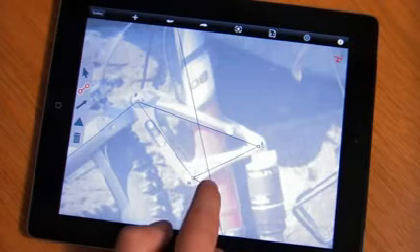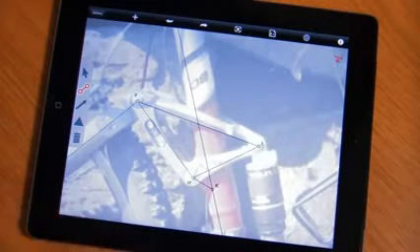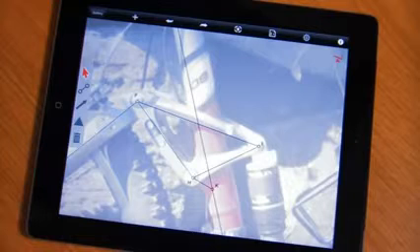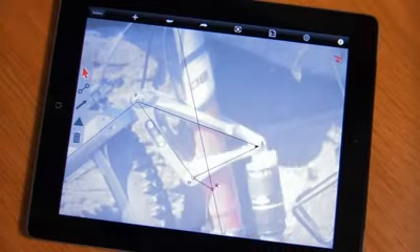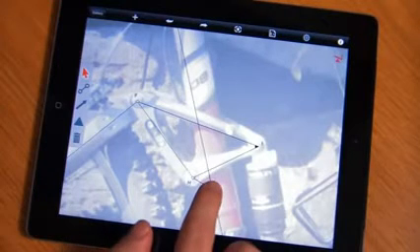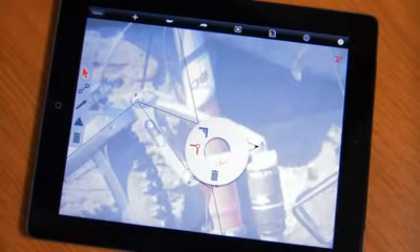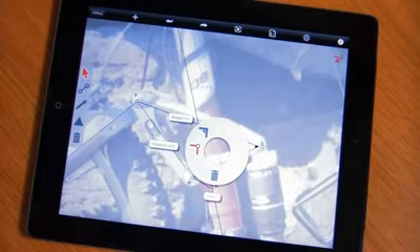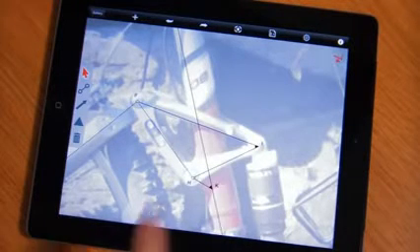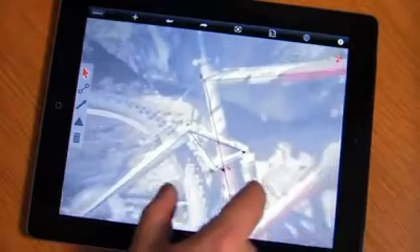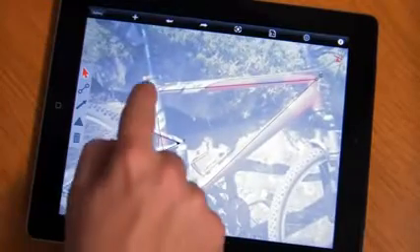Now we can add an element to attach this rocker to the frame. One of the other capabilities we've added here is the ability to weld a joint. So if you don't want it to be a pivot pin joint, you can simply weld it in place. If you're not sure what the commands are, we also have an automatic tooltip that pops up to show you what the description is. If you click on the tooltip, that'll actually take you to the help topic referencing this particular tool.